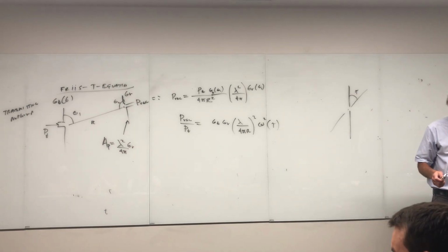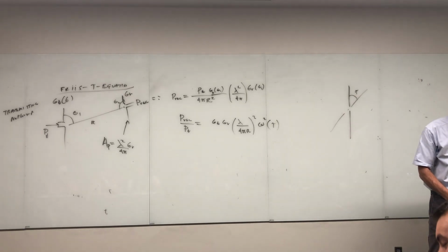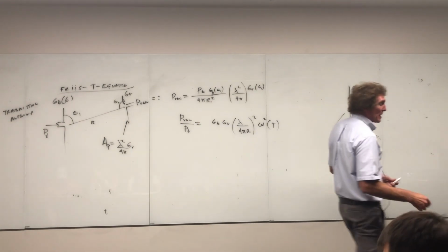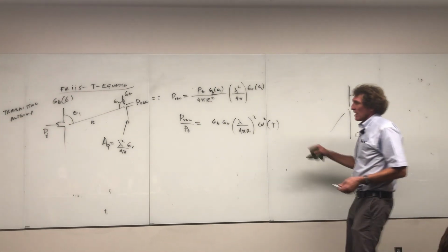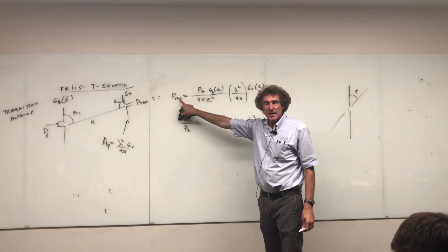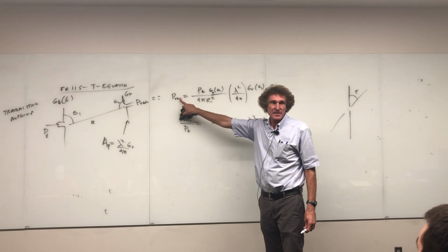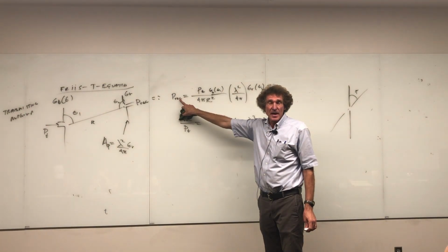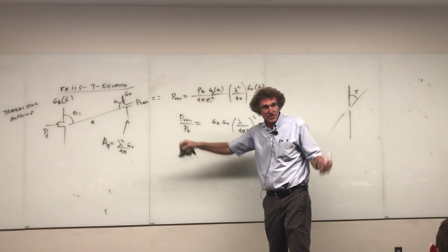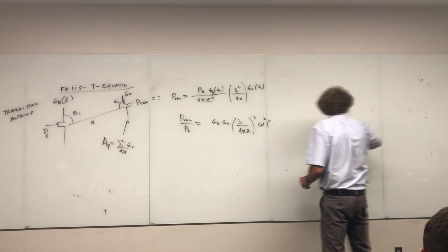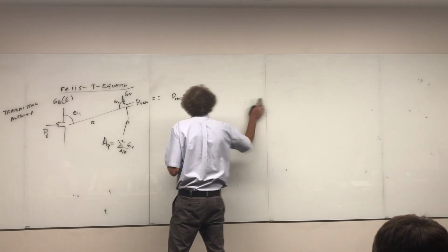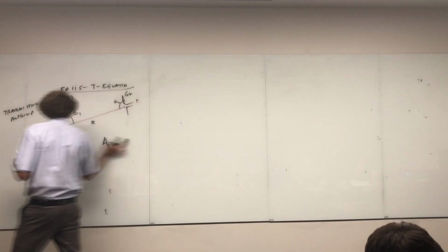All right, next we're going to talk about, that's Friis in a nutshell. Now, how much power can you receive? This is important. We talked about P received here. This amount of power is received, but this is the problem that's disturbing. That's not the amount of power you can actually get out of that second antenna. That's how much is received. At best, you can get half of that power out. The other half is re-radiated, and I'm going to show you how. Depending on who teaches some of these courses, they don't always go over the finer points. I'm sure Riggs and Wentworth will.